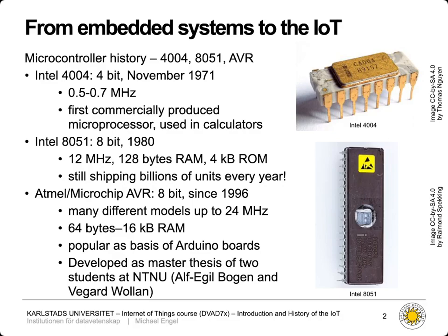It has very many different models, which start at very small amounts of RAM, 64 bytes for very small and cheap applications. But you can get controllers with RAM up to 16 kilobytes. And you've probably seen the Arduino boards before, so the AVR microcontrollers are used as the basis of the Arduino boards.